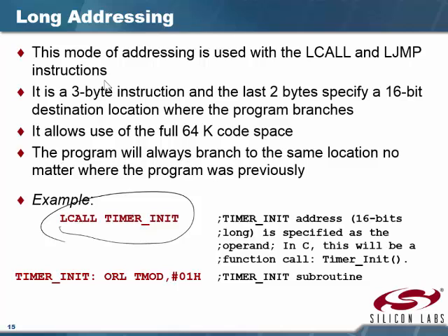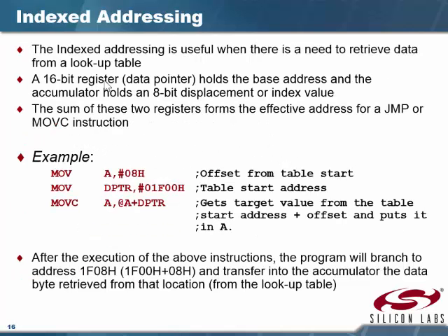We've got the absolute call, which means we're staying within 2K, and a long call, where we can go anywhere we want. You've got to remember that they came up with a lot of these additional addressing modes to try to save space. If you're going to do a short jump, use a short call. If you're going to do a medium size, you do an absolute. And if you're going to do a long jump, you use the long call or jump.